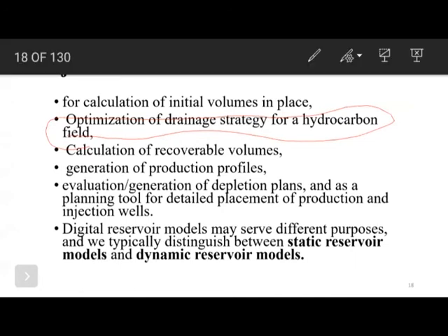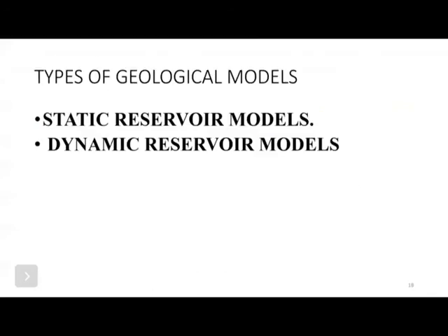A digital reservoir model may serve different purposes, and we typically distinguish between a static reservoir model and a dynamic reservoir model. These two types of geological modeling are the key points we need to understand first and then create. In this training, we are going to move through these two types of reservoir modeling, but mostly for Petrel, as I've said, we are going to stick to static reservoir modeling. So we're just going to create a static model.